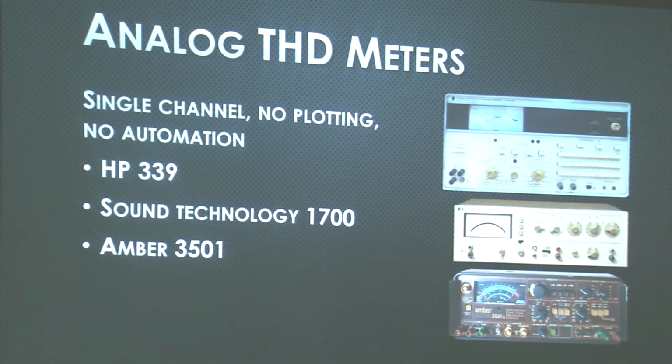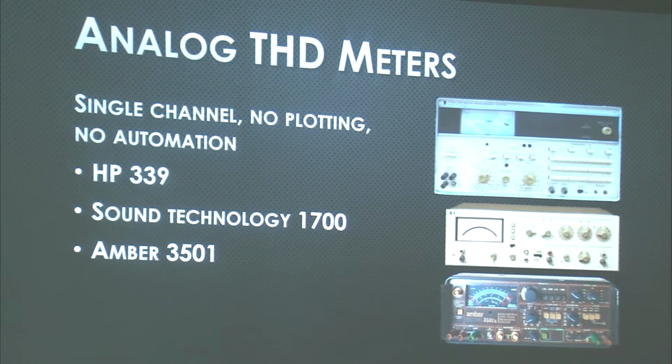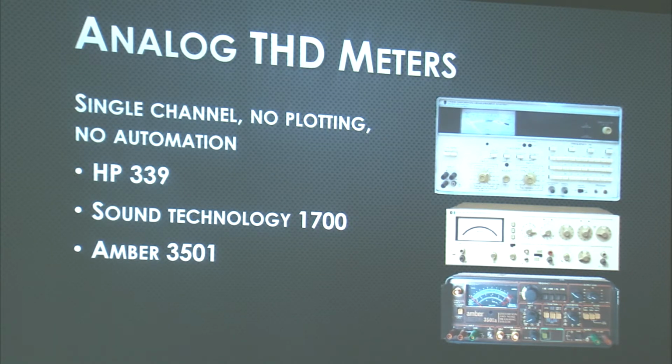I'd warn you on the Sound Technology because the coupling between the oscillator and the analyzer is mechanical behind that huge array of push buttons. If something gets out of line there, you're in deep trouble. Otherwise, they're fully maintainable and there's nothing terribly exotic in there.